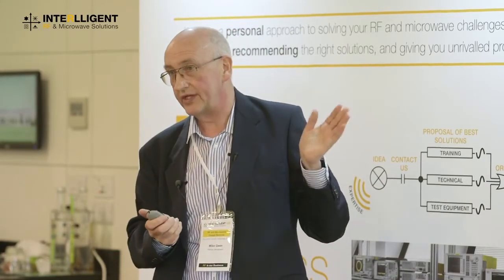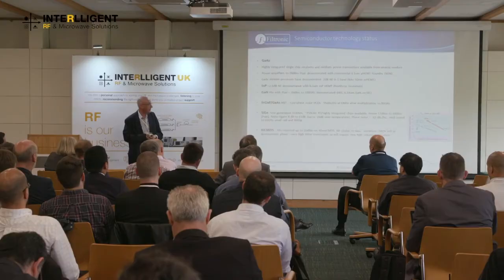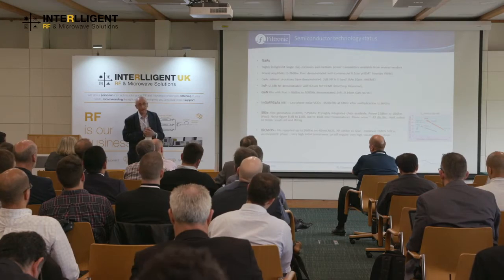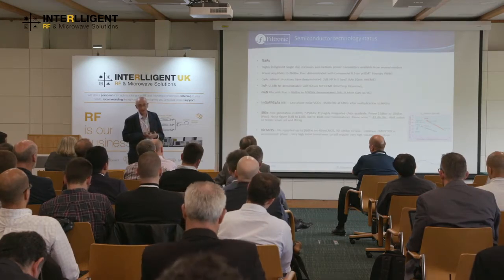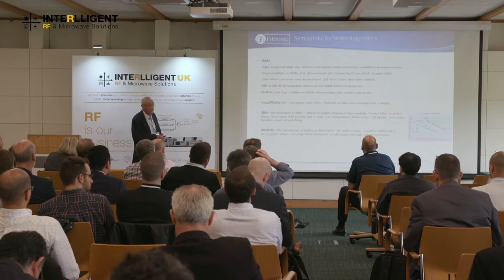Now, Filtronic is technology agnostic. We're not wed to any particular semiconductor technology. We'll use whatever's available and whatever works. But the fact of the matter is we have yet to find a silicon germanium chipset that will meet the specs that the customers are placing on us. If they did, we'd use it, but so far, every silicon germanium chip I've seen needs a GaN PA and usually a GaAs PA and a GaAs LNA in order to get the performance. BiCMOS is actually coming up very rapidly, and there are some quite impressive results being quoted on BiCMOS. But again, it's going to be limited in power.